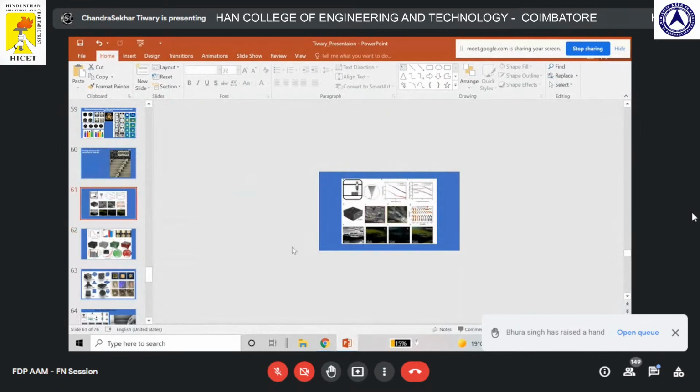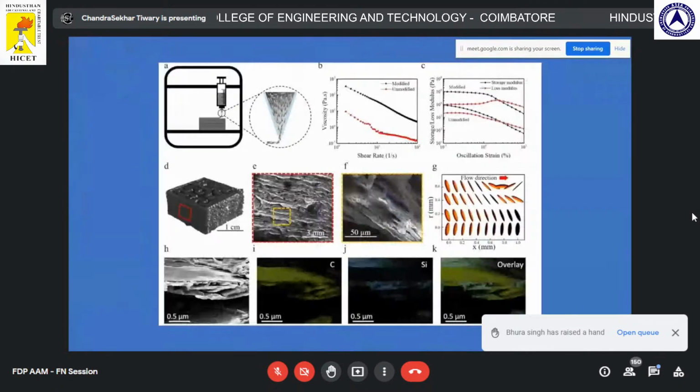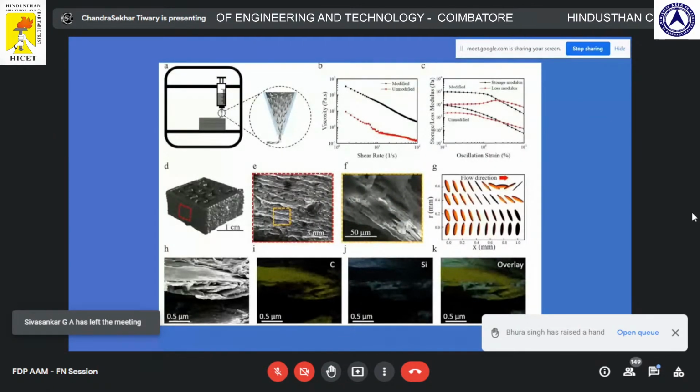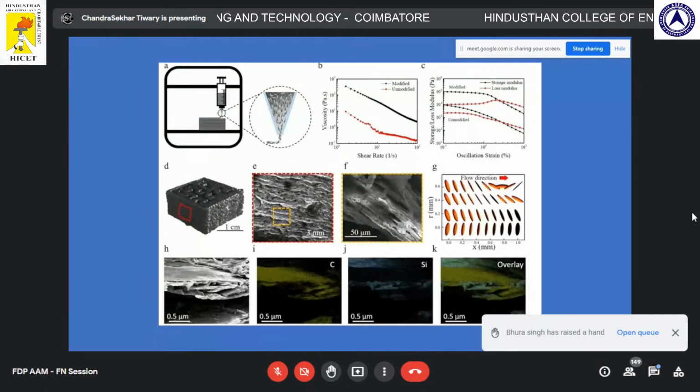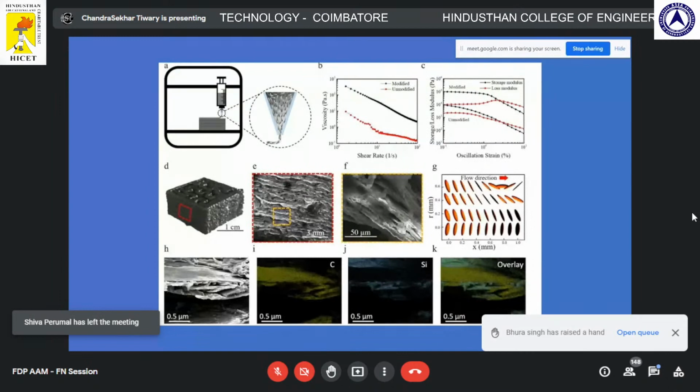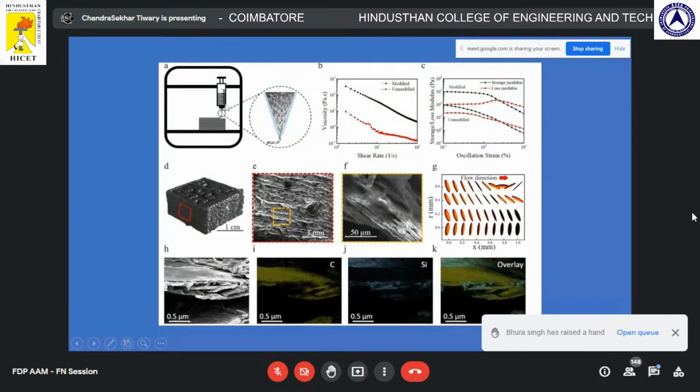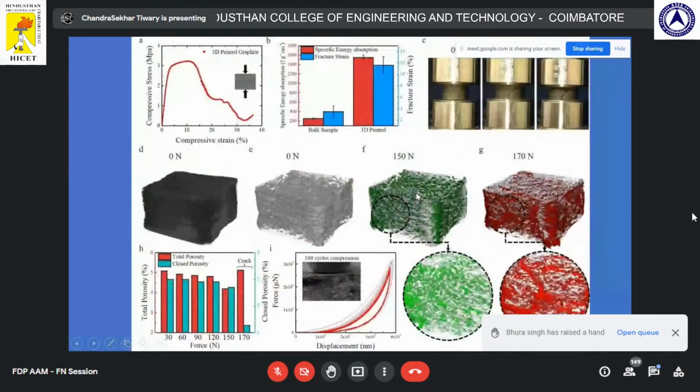Okay. So coming back to graphene, putting them together, or even graphite, printing them is difficult. But if you take the graphite and turn it into graphene, we can make an ink, and this is direct ink printing, where we can make a solution of graphene and then print it. We print them, try to understand the mechanics and how they print, and all of this is detailed in the paper. We look at porosity, look at how the deformation happens when you deform the graphene printed block.